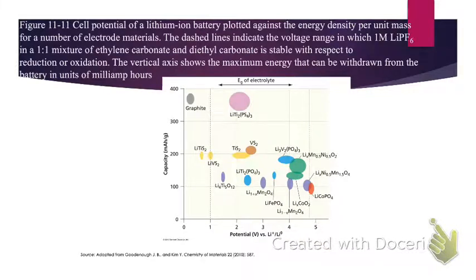This diagram shows the potential generated by the lithium-ion battery with different types of materials. We were talking about, for example, 3.7 volts as being on the order of the maximum associated with this, so in this region here, 3.7 volts. Again, there are different materials, different types of electrolytes, and electrodes being used and developed to help maximize the output of these batteries.